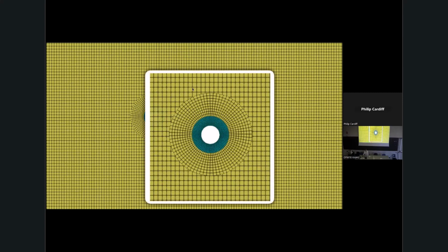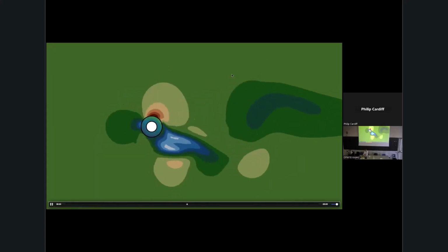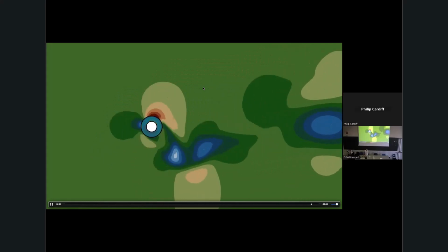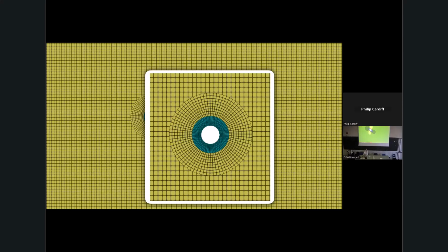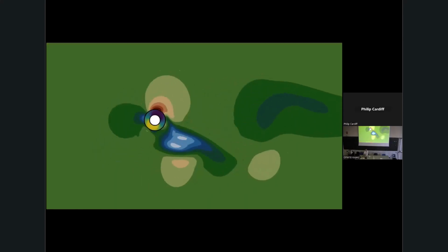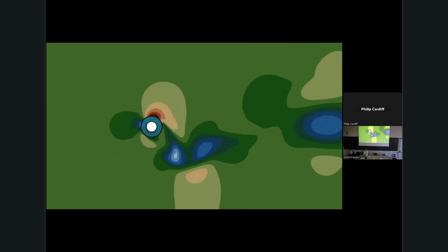Just to zoom in, you can see here's the overset mesh and the background mesh, and this is the solid mesh in a different color. You can see it's a non-conformal interface as well. From an FSI perspective, overset is good because the FSI procedure doesn't need to know about overset, because the FSI interface is independent of the overset interface, which is purely in the fluid solver. If you run this case with some artificial properties, I'm moving it back and forth so you can see the little rubber donut bouncing around essentially. Because it was imported, this was actually using preCICE to do the coupling.